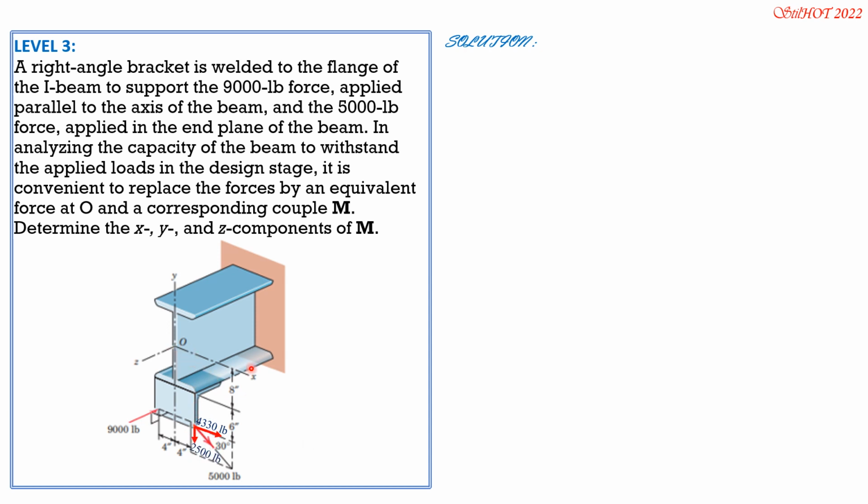So moment about X, 4,330, it is parallel, so no moment. 2,500, because it is on the end plane, it passes through the x-axis, so no moment. Same plane as xy plane, so no moment about x. Only 9,000 will have moment about x.